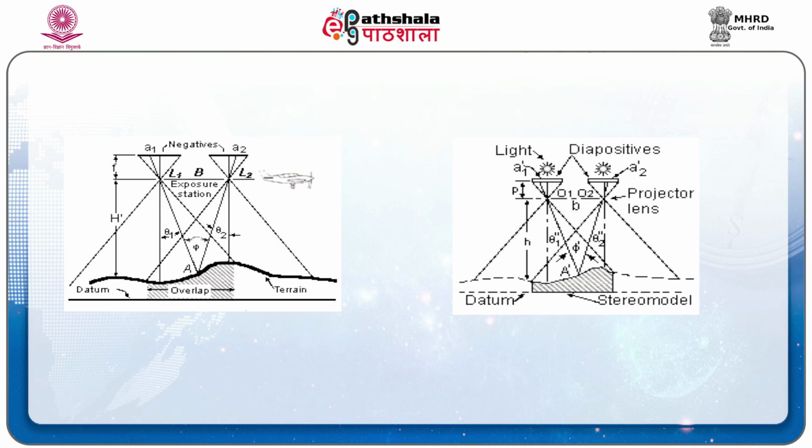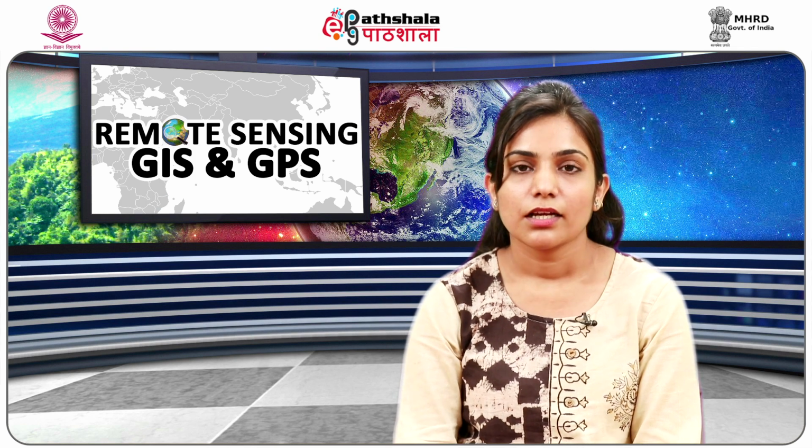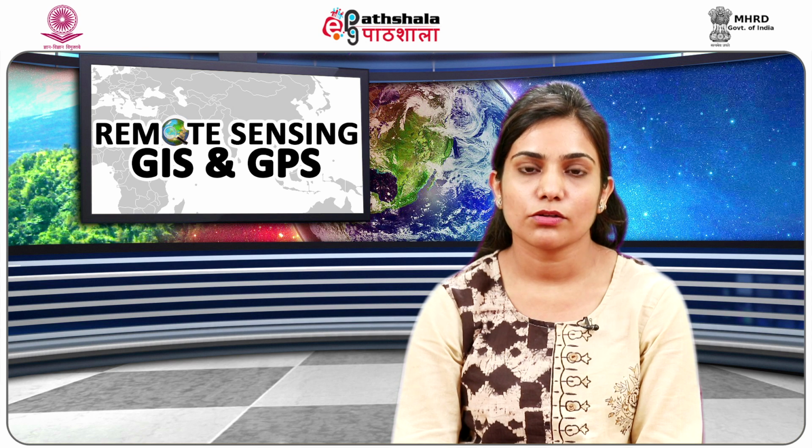The parallax difference can be used to determine the height of the object and the depth and slope from the stereo pairs. Next information we can derive is to measure the height of an object above or below a reference point. From a stereo pair of aerial photographs, the following data is required. First is flying height above a reference point. Second is photo base, which can be measured from the stereo pairs. Third is parallax difference.